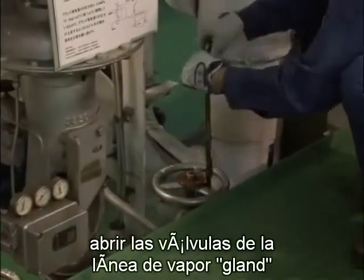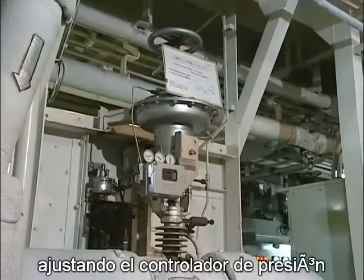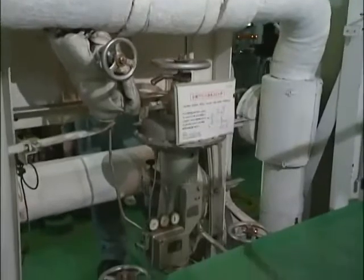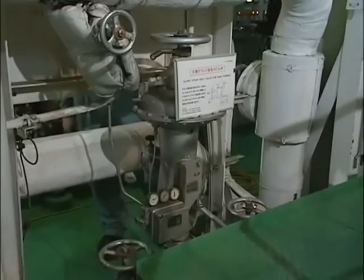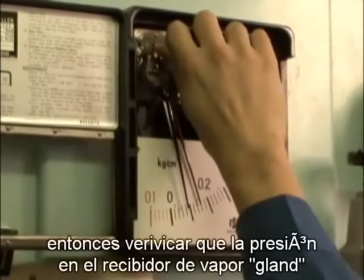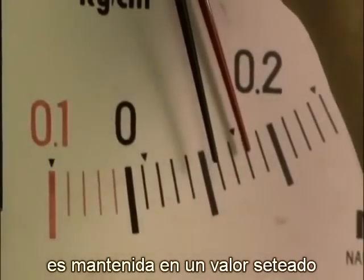Open gland steam line valves and operate the make-up valve and spill valve by adjusting the pressure controller. Then confirm that the pressure in the gland steam receiver is maintained at a setting value.